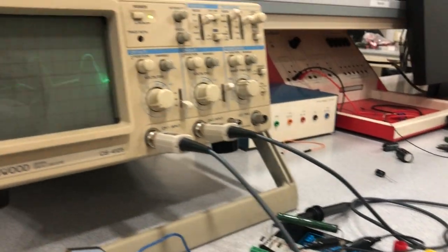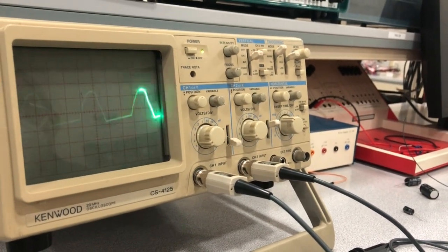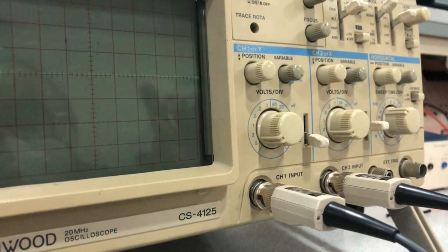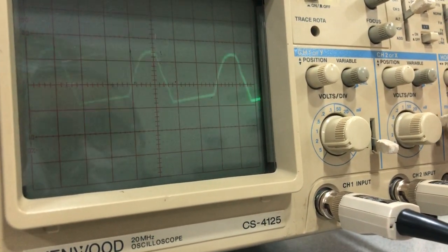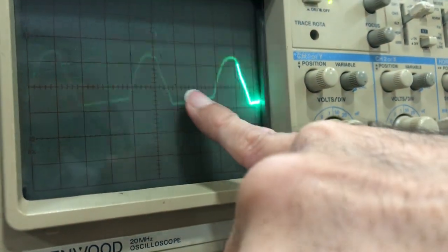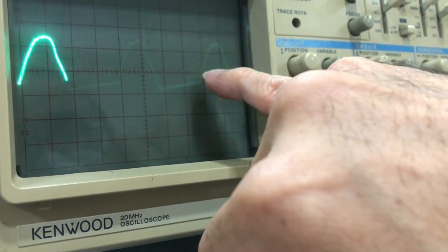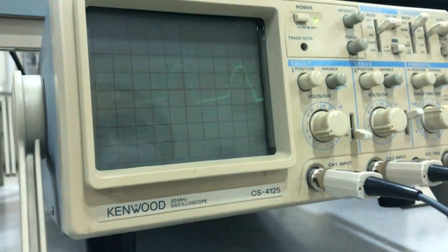It basically eliminated the DC average from the signal, and now the signal is symmetrical around my zero line. When I go to ground, this zero line I have centered on the middle horizontal line. It took out the DC, so now the area below is equal to the upper area above. So the average of this DC pulsating signal is taken out and I'm seeing it balanced.